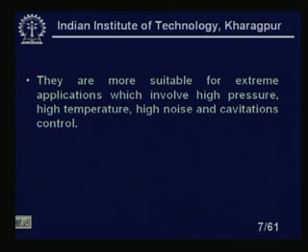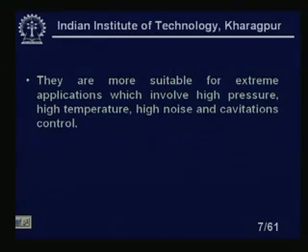They are more suitable for extreme applications which involve high pressures and high temperature, high noise, and cavitation control. Cavitation we are telling repeatedly, we will study the details after a few slides. It is very important for control valves, you must know it in great detail. So they are most suitable for extreme applications which involve high pressure, high temperature, high noise, and cavitation.